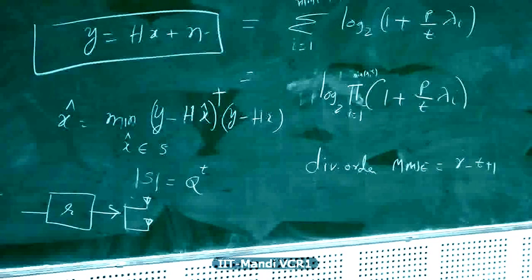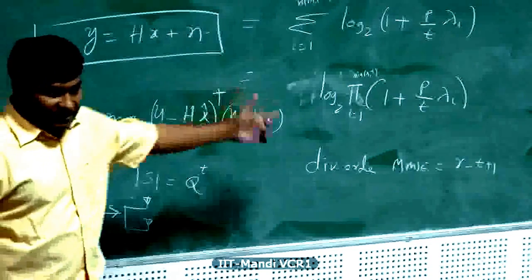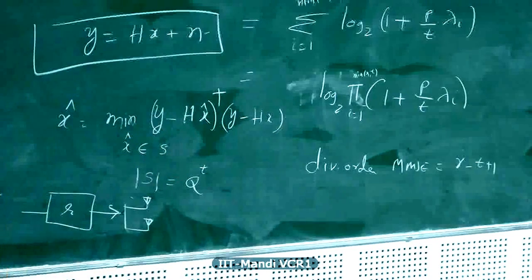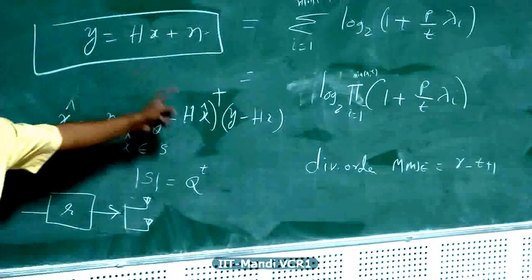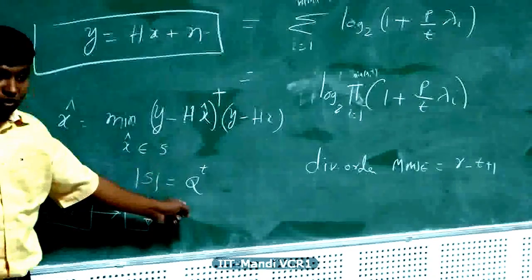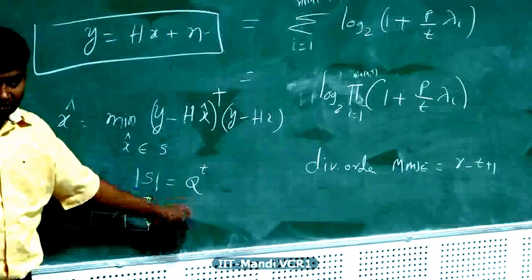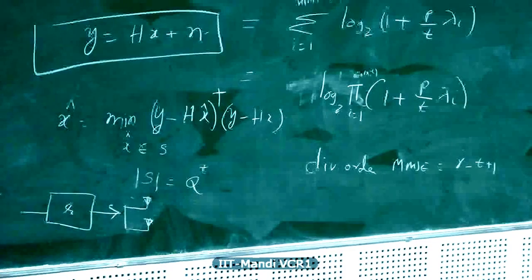If you have CSIT, the problem is simple, encoding and decoding. That is, the channel state information at the transmitter, H. If you don't have H, then MMSE is one candidate with spatial multiplexing, or you can also have this so-called MLD receiver, which is considerably more complex, right? Okay. So this sort of concludes the discussion on MIMO, except for one little thing we have missed.